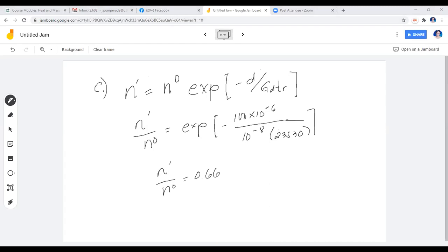It says here, the percent of the nuclei removed in the discharge by the time they have grown to 100 micrometer. This number is still accounted for because it's based on the diameter of the crystal, the growth rate, and the residence time. This is the one remaining inside the crystallizer.